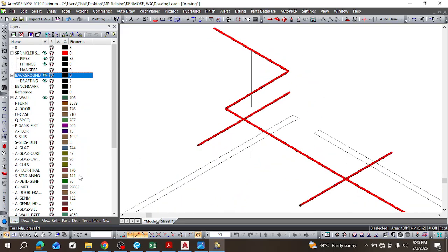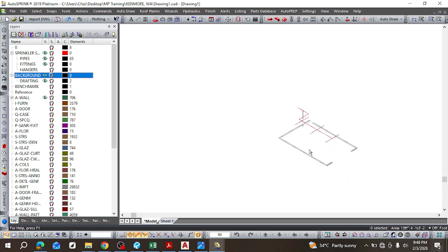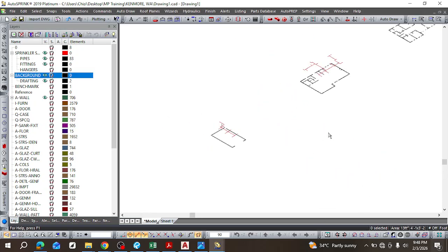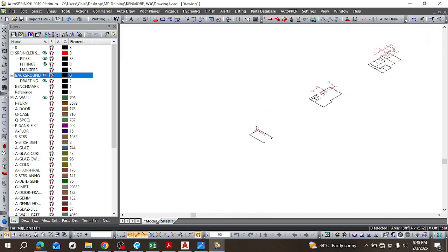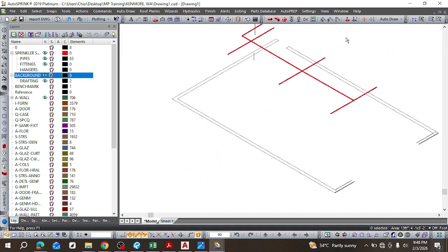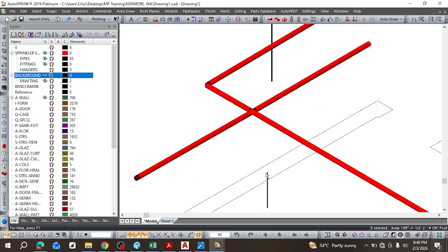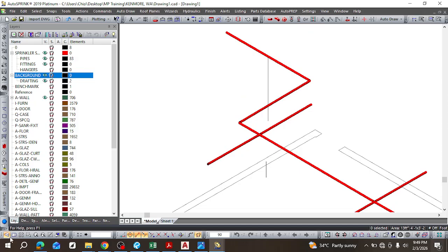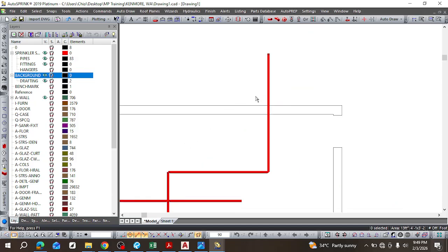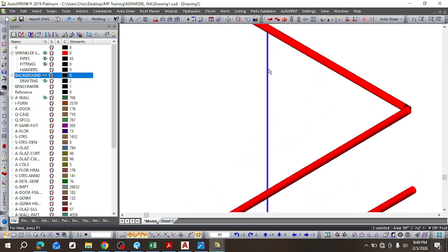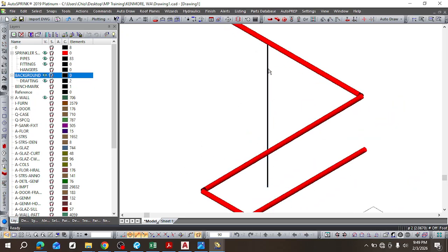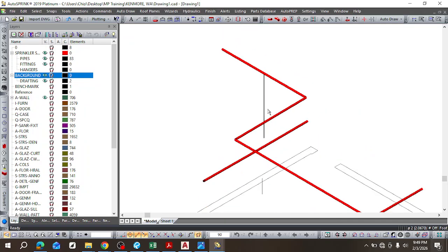So let's look at it from here. You see that this thing is taking shape. This one is at a different height. Let's just finish it. All I'm trying to do is align all the plans above each other. So let's confirm that this is where we want it to be. I drew the line around here, so I will select this point and see whether the line gets selected. It's now blue, so it got selected indeed. Escape, it's no longer selected. I'll now extend this line up and see what we can get out of it.